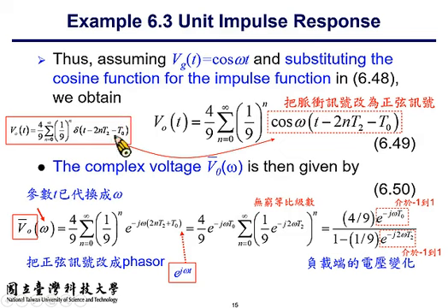So the thing here is simply to replace the delta function with a sinusoidal function with appropriate description of the time delay within the function. So it becomes cosine omega times t minus 2n T2 minus T sub 0. So here we use the superposition law to substitute the impulse function with a sinusoidal function, which is used more often in actual communication systems.